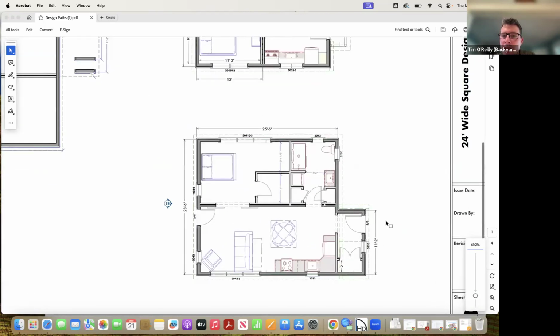So on our bottom floor plan, a mudroom and entryway was a big key. So we bumped that square out. We added a couple extra square feet, but now they have a landing zone. They come into the house, they have a deep storage closet, and they have a place to kick off their shoes before entering into the rest of the house. And so when we're designing in these small spaces, they're dedicating maybe 80 to 120 square feet, depending on how big that space is, but it's getting that storage where you need it. So in that small space, this house probably won't be too cluttered if when they come in the door, all the things that they bring are stored immediately where they need it.